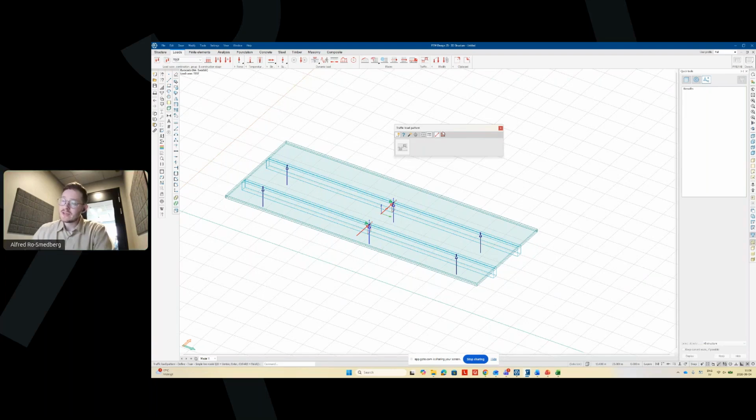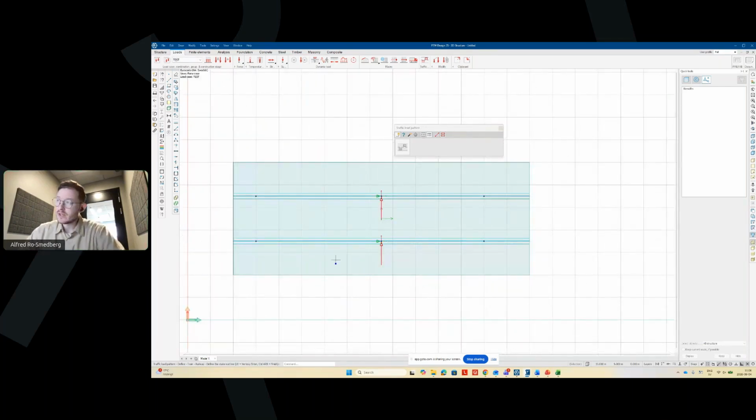If, as in my case, you have a slab and you want to get some depth for your traffic loads, then the railway option is the way to go. So let's use that one today. And actually today, the goal is to set up 2 railways on the same bridge. To do that, we have to start by going into the default settings option. If I were to start drawing right now, then the default setting is set to just 1 railway, so I'm limited to just 1 railway.